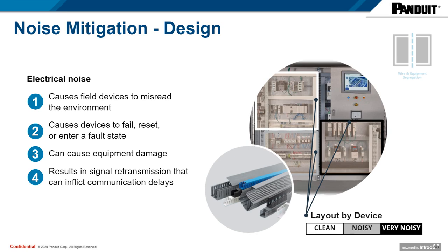It's best to segregate noise sources and cabling, that is, components such as VFD drives, servo drives, switching power supplies, etc., from noise-sensitive devices such as communications wiring, analog signal wiring, high-speed counting signals, sensors, protective devices, PLCs, etc. This is also referred to as zoning the panel.